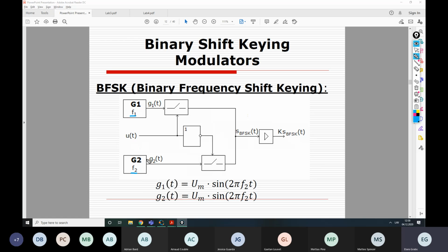Of course, we will now speak about how we can simplify this, because having two generators is not really good, because each of these generators is subject to its own instability, and it would be much better if this instability would be the same. However, if these blocks are separate, two different devices, then there is no way we can find these blocks in such a way that they would have the same instability. So that's the purpose, to merge them somehow into a single source, and then they would share the instability.